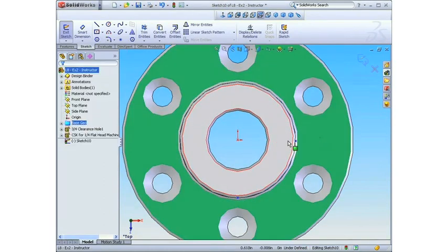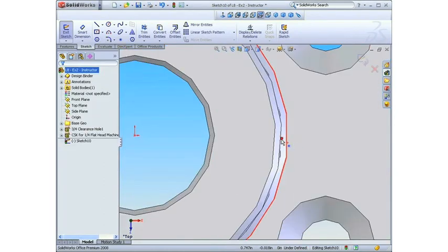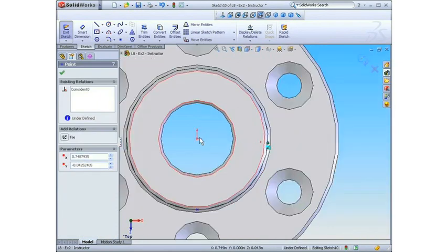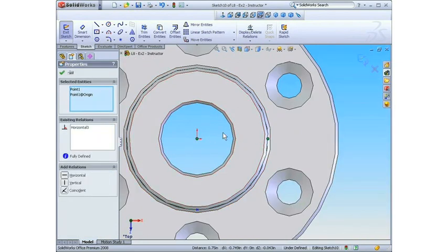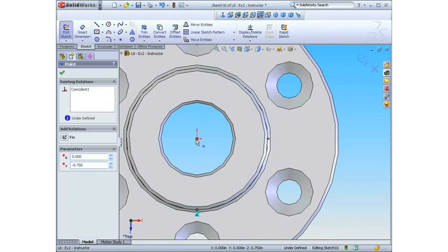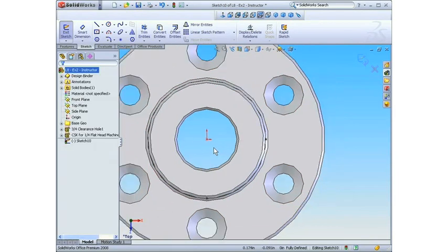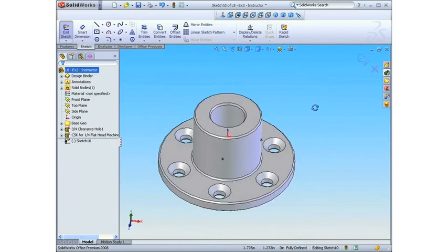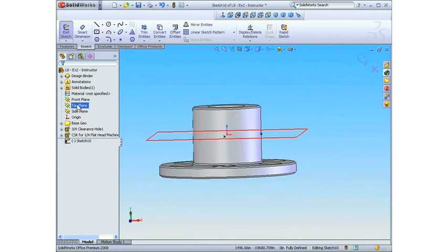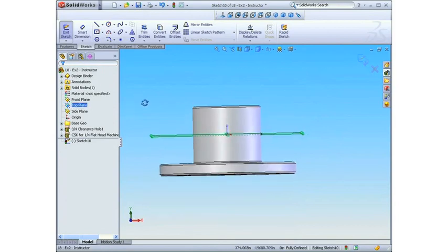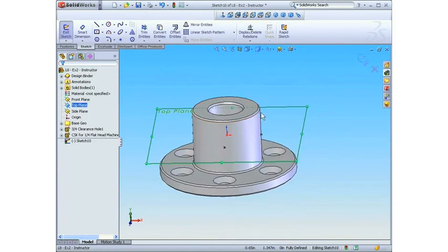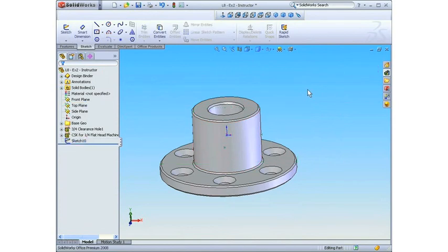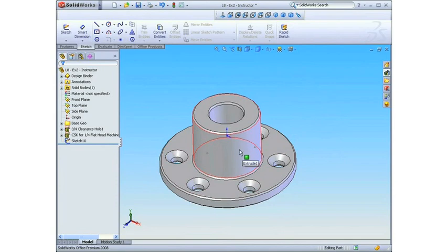Sorry, it's difficult to see what's going on here because of the chamfers. But to the outer surface, and I want those points to be horizontal from the origin and this point to be vertical from the origin. So they're now fully defined, and they're on the side faces of my part because I sketched on that top plane that cuts through the middle there, and I created them coincident to that outer face. So I can save and exit that sketch. Now I have the 2 points where I want my holes to go.